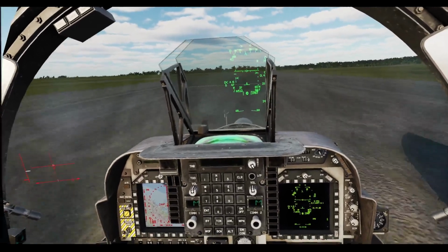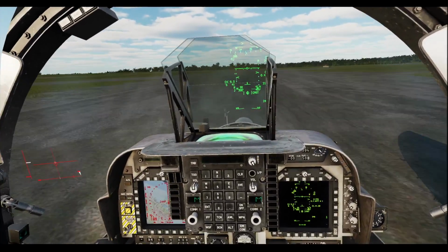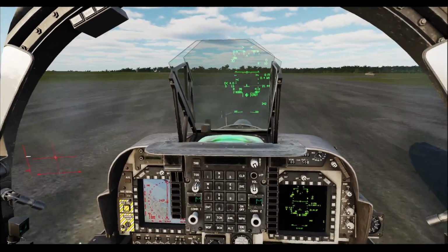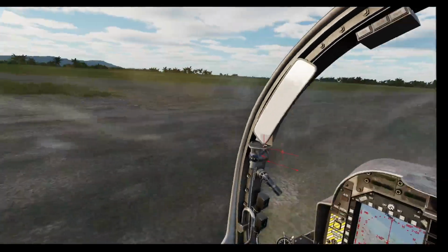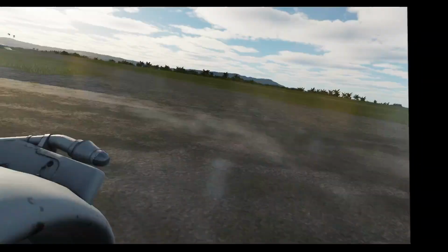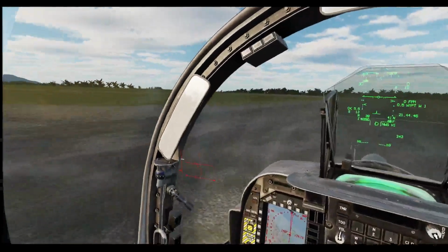close the throttle, reset the nozzles, and apply the toe brakes. Keep the aircraft going centralized until we're at a reasonable speed, center the rudder, and then use nose wheel steering. Caution. And engage the nose wheel steering in the anti-skid position. And we can clear the runway.